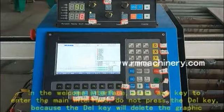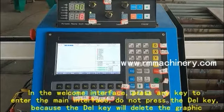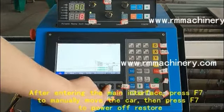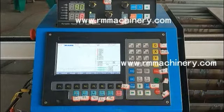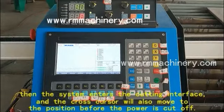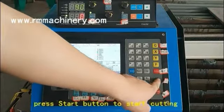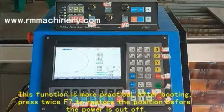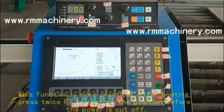In the welcome interface, press any key to enter the main interface. Do not press the delete key, because the delete key will delete the graphic. After entering the main interface, press F7 to manually move the car, then press F7 to restore after power off. Then the system enters the cutting interface, and the cross cursor will also move to the position before the power was cut off. Press the start button to start cutting. This function is very practical. After booting, press F7 twice to restore the position before the power was cut off.